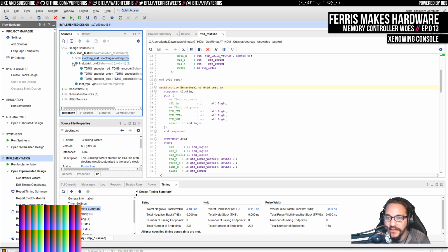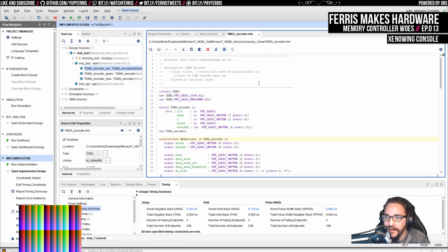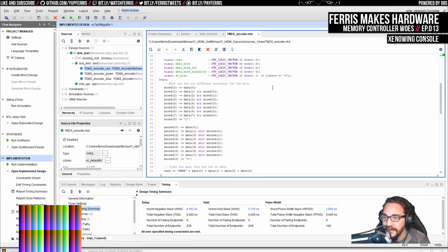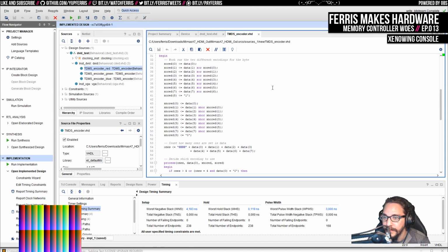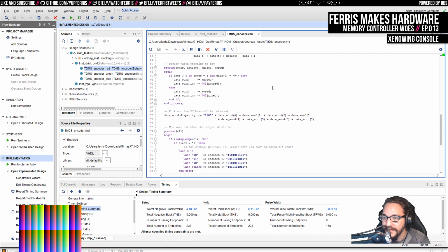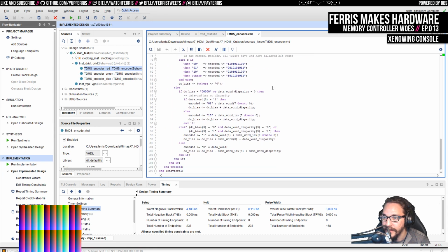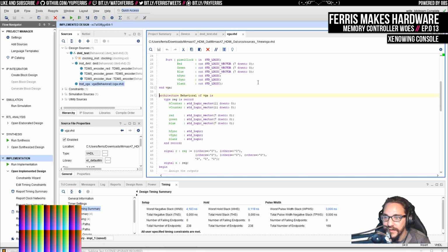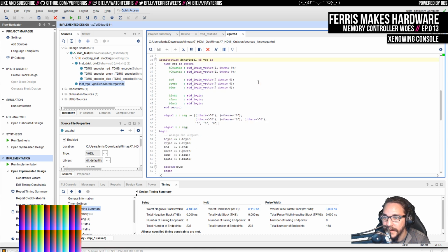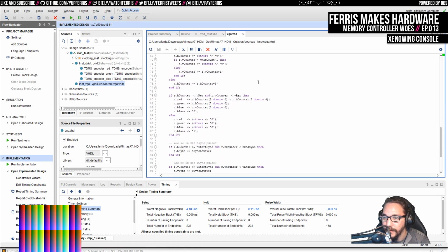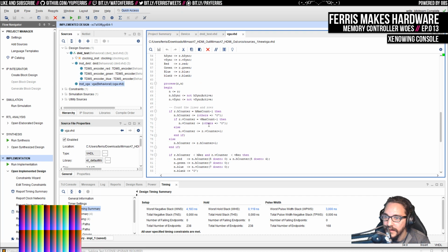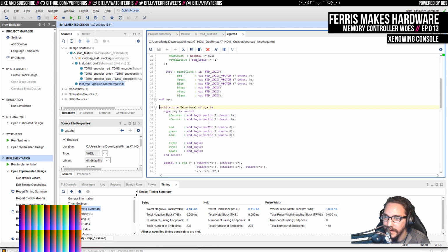And then these different video signals here. There's this TMDS encoder, which has this clock data C blank encoded. I don't know what this means because I haven't really looked at TMDS at all. But I guess this is it. Just does this basic encoding at 125 megahertz, however that works. And then we have the VGA part, which should be quite simple. Because this should just be a bunch of counters, and then whether or not you generate the different active signals, and also I'm guessing there's a data enable signal here. I'm not actually sure.